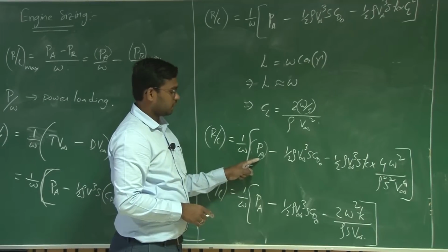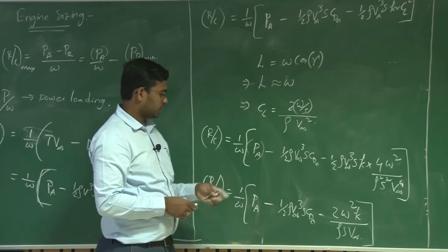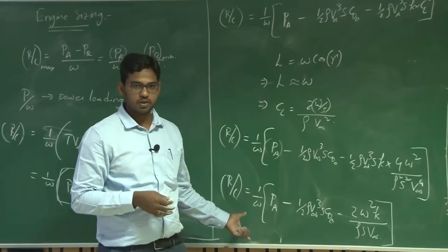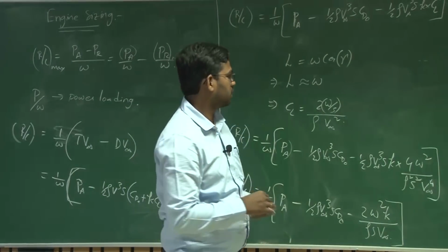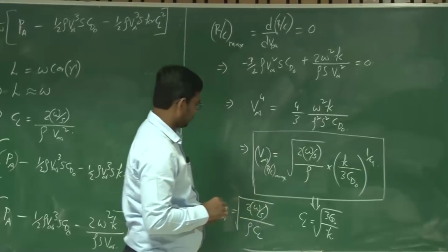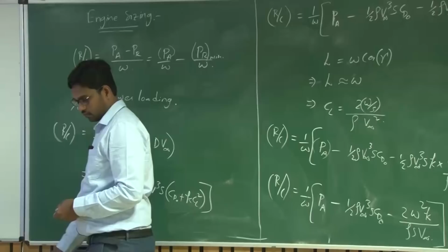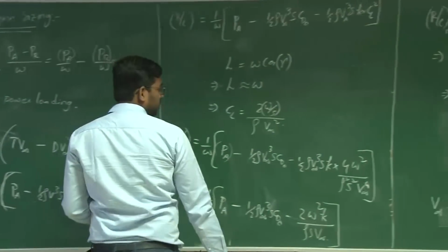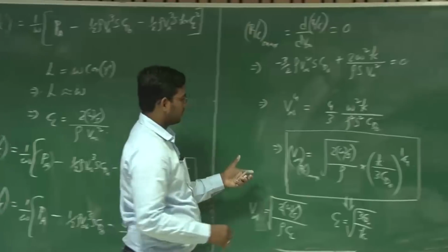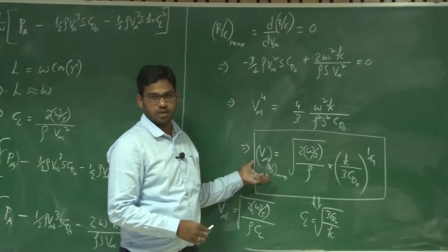This power available is shaft power times the efficiency, and moreover this efficiency factor is also assumed to be constant with velocity here. So, you know the corresponding velocity for rate of climb maximum, right.